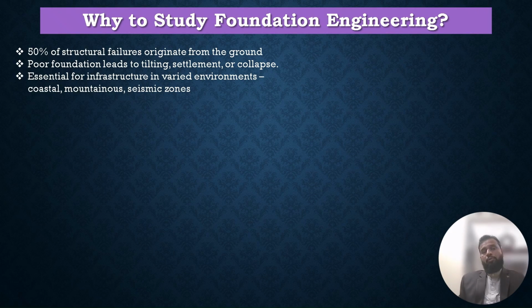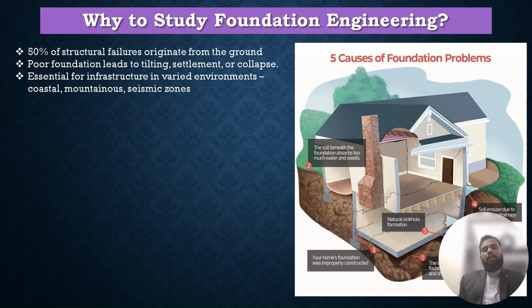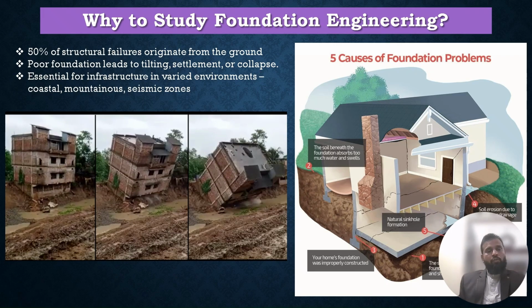So foundation engineering is also essential for infrastructure in varied environments like coastal, marine, or mountainous regions, especially seismic zones. A more common cause of foundation problems is the increase of moisture and its interaction with the soil beneath the foundation. It leads to shrinking and swelling of the soil, which leads to cracks and differential settlement, normally on the floor slab or maybe the joints of the column and slab. So we need to carefully observe these factors.